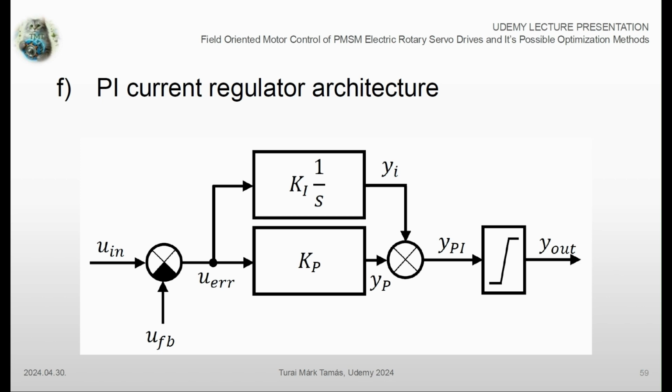Anyway, this nominal voltage value is going to be a boundary for our system, which means that we shall ensure that the current controllers do not output higher voltage references than the available DC-link voltage value. The same saturation need is going to be present in the previously mentioned speed control as well. However, the limitation there is going to be the maximum rotational speed of the PMSM motor.